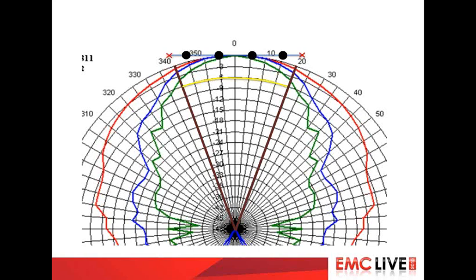What we're looking at there is, you see the red radiation pattern and its beam width, its lobe shape, and then you see the blue, and then you see the green. You see they get narrower and narrower and narrower. What that yellow line means, it's a keep out area. Below that yellow line and within the segment marked by the two brown lines is a keep out area. Your beam is not allowed to fall within that area. Because by definition, if it's 0, you're at your minimum, you're at 18 volts per meter. You must have exceeded 36 volts per meter for the beam, which is going to end up where those red crosses are. It cannot be more than 6 dB away, because it would then be in excess of 36 volts.